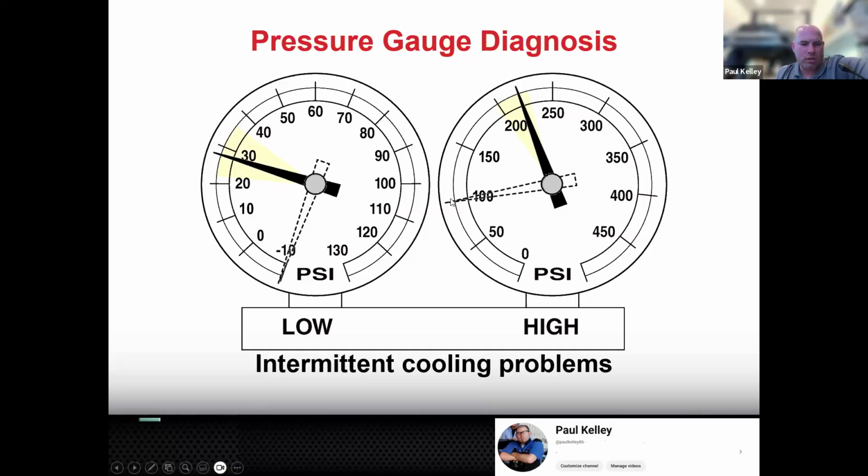I thought if there was a restriction, the high would spike too high. And the truth is it would for a short time. It would spike too high, but then remember, the only reason it's high is because it's got a supply of refrigerant on the low side. Once the compressor's starving for refrigerant, it's not going to be able to build the high that high. It's actually going to be low.